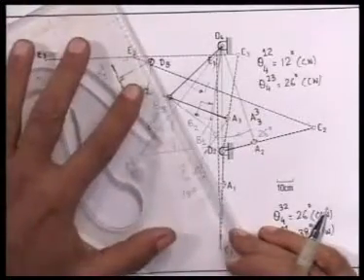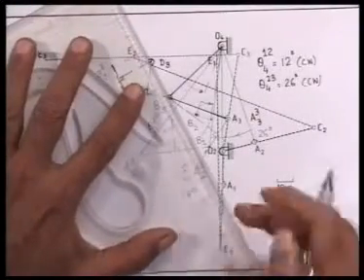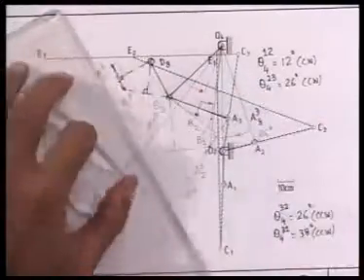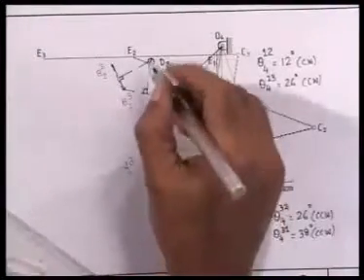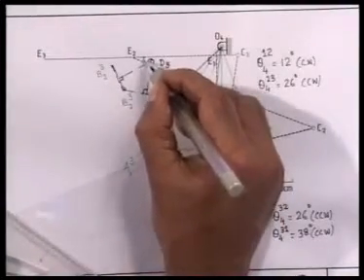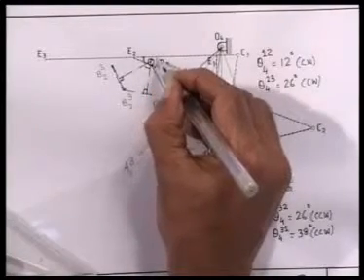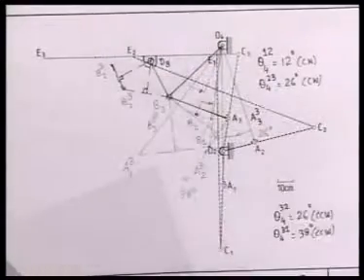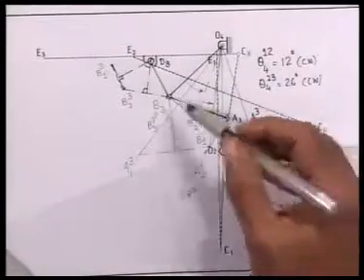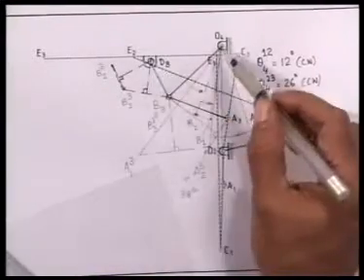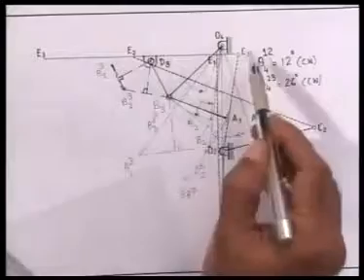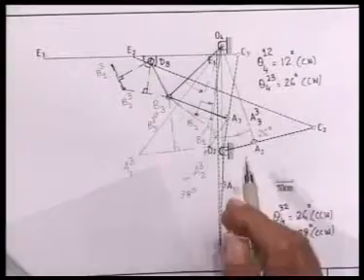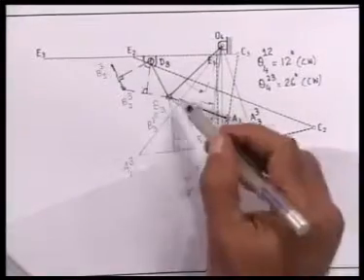So there is a rigid link connecting B3 and D3, and this D3 belongs to the door board, so I can have extension of the door board like this. So we have determined O2, A3, B3, D3. O4 was already chosen and C3, E3 was already chosen. This completes the design of the 6-link mechanism for the door board, namely O2, A3, B3, O4, D3 and C3, E3,